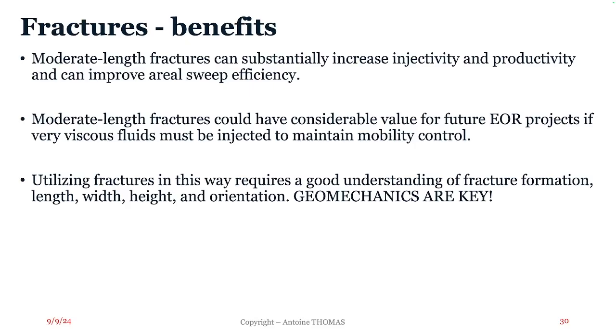So this is the idea, and you really can get a lot of value for injecting your polymer if you have some fractures, or if they are here, but if you know in which direction they are going, because you will gain injectivity and then you will be able to improve the sweep as long as they don't, of course, connect the injector and the producer.